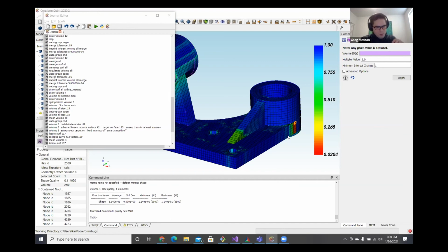I recognize that, especially with topology optimization, or say that you're taking a mesh from a previous simulation and you're trying to operate on it. My suggestion there would be to use an STL-centric CAD software, like MeshLab or similar software, to do any of the Boolean operations that you need to do beforehand. Those typically are more robust. We're trying to get more robust in mesh-based geometry, and we're looking at maybe alternatives, but we just don't have the best solutions for mesh-based geometries today.